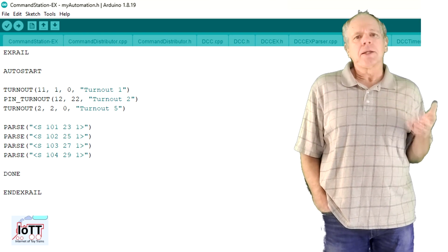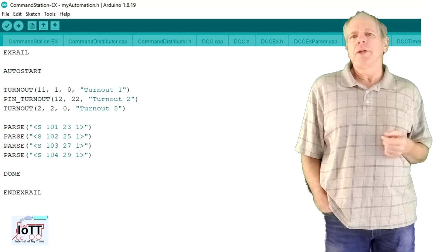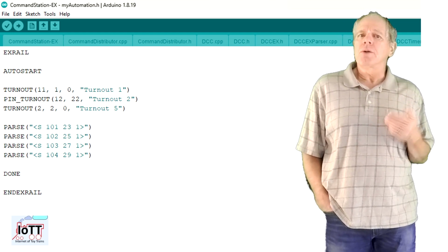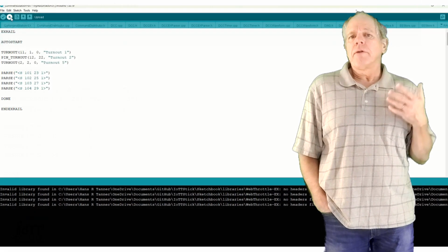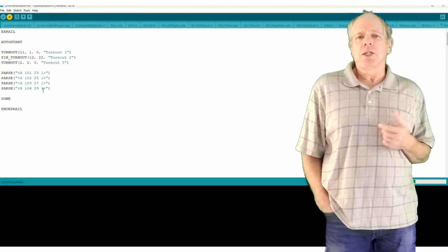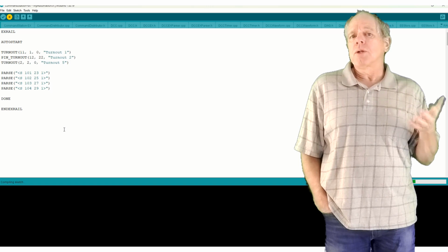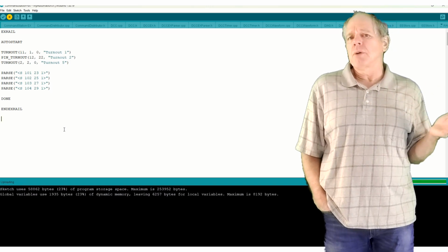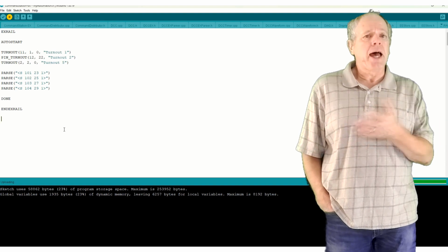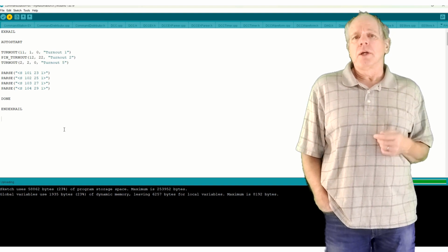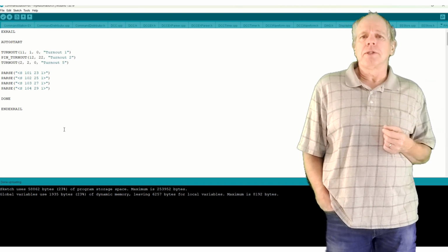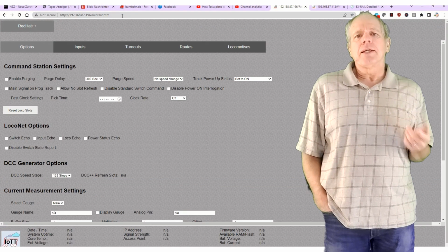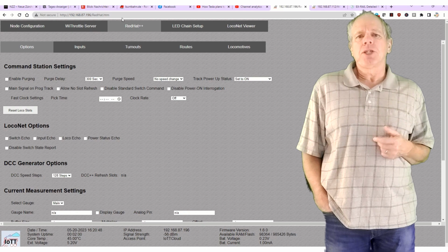I now compile the code and upload it to the Arduino. Note that the IoTT stick may have to be disconnected or at least switched off when uploading the Arduino sketch, so that it does not block the serial port. This is not consistent though. I have some Arduinos that work with the stick active and others don't, so you will have to test with your own setting.